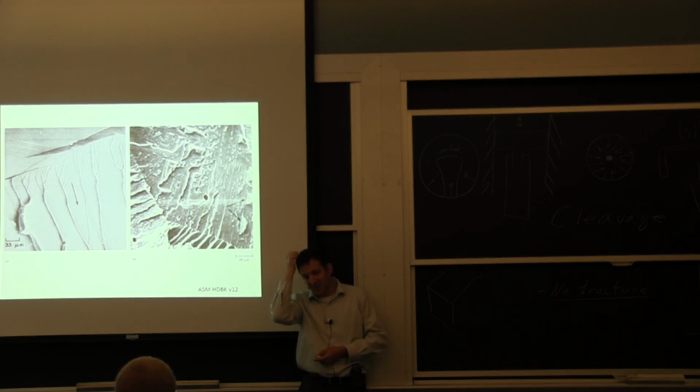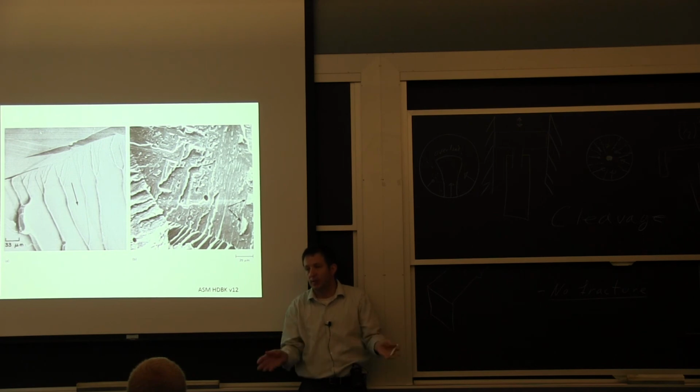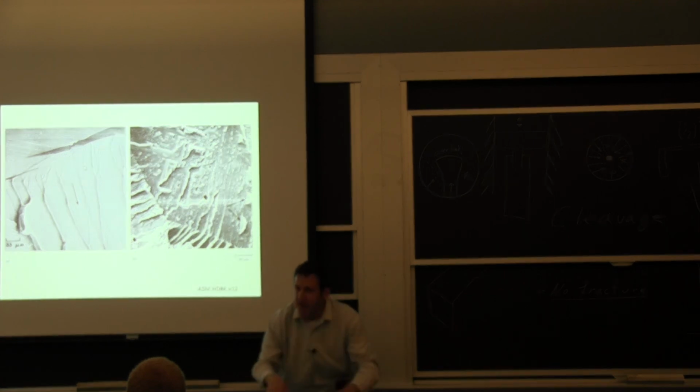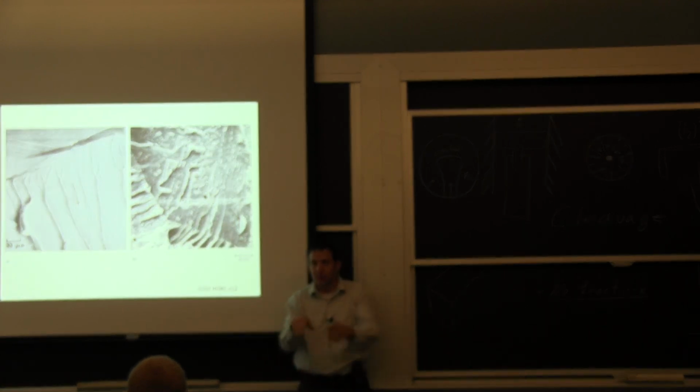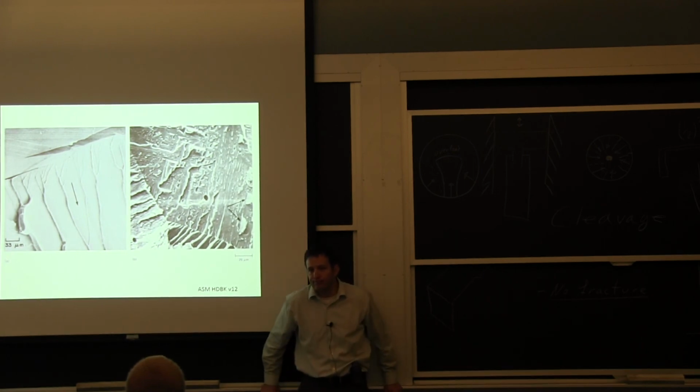You could also call these crack propagation lines. This is one example, looking at high magnification under the microscope, where the lines are spread out and they come together. So they converge instead of diverging. The idea there is to reduce the number of steps, because each step between different planes consumes a lot of energy. You need flow of the material there. So if you cluster them together, you're reducing the overall energy it takes to fracture.